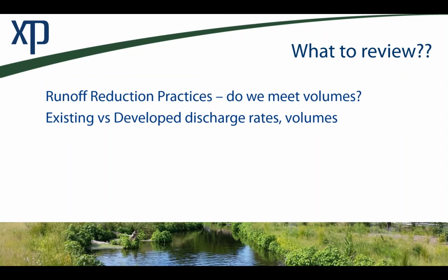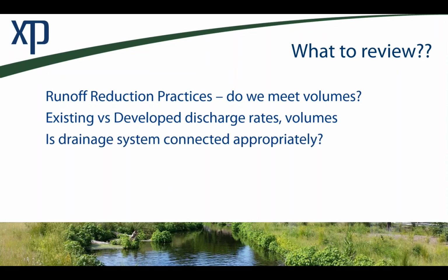A bit of a hydrogeomorphology viewpoint, so hydromodification. Beyond just the bare minimum of do we meet the volume to treat our pollutants, and are we not creating impacts beyond what the existing site looked like, is our drainage system connected appropriately? Sounds pretty basic, but often really difficult to see.